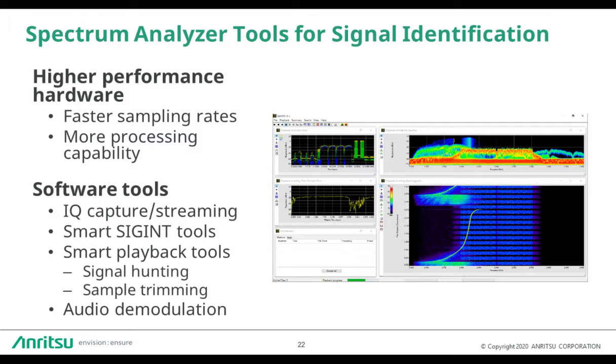When you hear those noises coming through, it may not be that you're hearing an actual transmitted audio signal, but you might hear some of the waves in the audio or clicks and pops. Things like that can tell you what type of interference you're looking for, or random noise might let you know that it's something more random like an oscillator or alternator. So these tools are all very helpful in analyzing the signals.